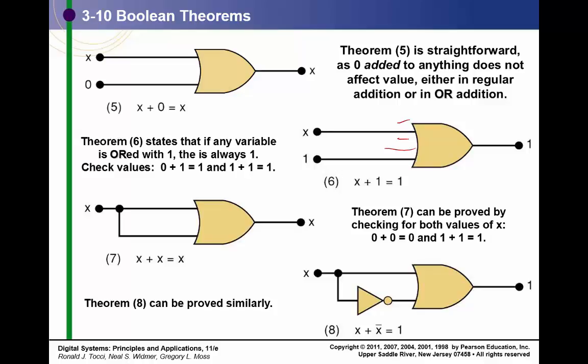And again, this circuit can also be used for detecting a negative going pulse, similar to what we have there. When this goes to 0, it takes some time before this one goes to 1. So we have a very short period where the output is going to be low. It depends on what technology you're using. It can be 4 or 5 nanoseconds all the way up to a millisecond with very old technology.